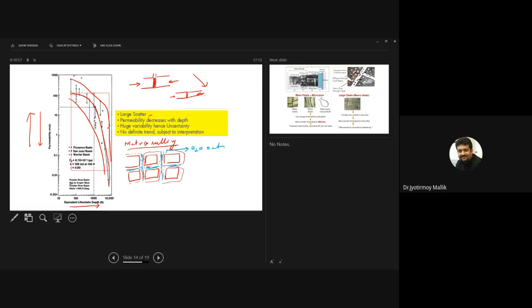That is what we talked about, right? And then there will be a point when gas will start to diffuse out from the matrix to the cleat system. Now, while this diffusion process takes place, when the gas molecules come out to the cleat, another phenomenon starts to happen, that is what we call matrix shrinkage.